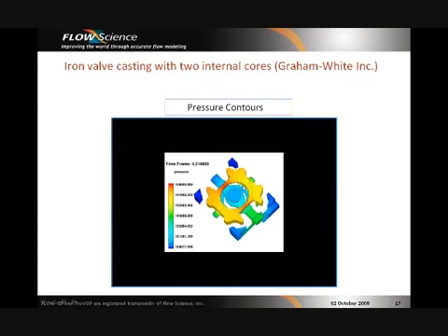Let's play this animation. It is quite clear now that the saddle core presents higher risk of the gas blowing into the metal as opposed to the T core, which generates the pressure closer to the prints and is a better design.